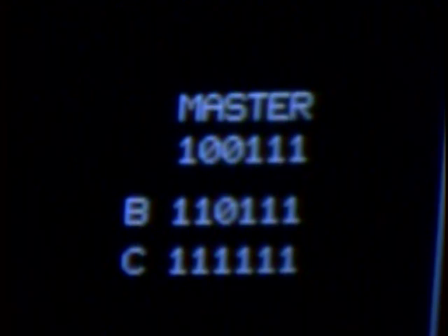For the 6 possible displacements and rotations, a 1 means the degree of freedom is fixed, a 0 means the degree of freedom is free. We now correct the boundary conditions. And B on the horizontal symmetry line means now the V displacement is free. C on the vertical symmetry line means now the W displacement is free.